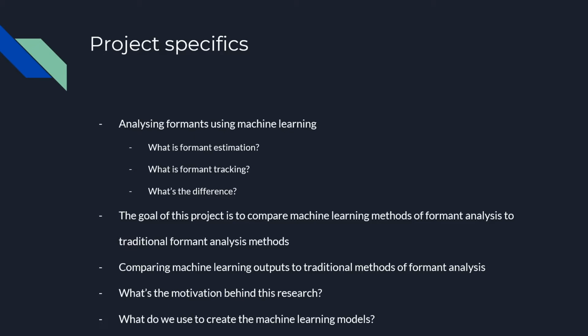The second is through formant tracking. Normally, speech is a continuous signal with respect to time, and we often want to track the formant values as time progresses, whereas estimation needs the full speech segment when the speech is already uttered to estimate anything from. Hence, formant tracking is the estimation of a formant's frequency tracks throughout an entire utterance, such as a sentence or a phrase. In this case, we will have a series of speech frames within a given time period that we want to analyze.